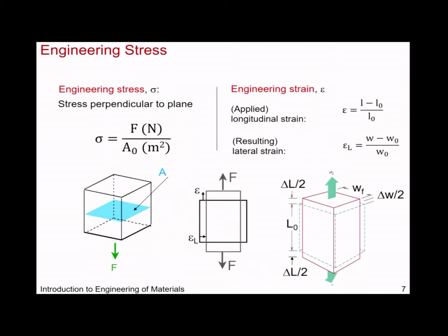So you'll see these equations quite a bit again and again. If you're applying a load in tension here with some starting material that has cross-sectional area A0, you can imagine that as it's elongating, there's going to be some contraction laterally, to conserve mass, right? You're elongating it, so now laterally it's contracting. And vice versa for compression, if you're squeezing something, you can imagine increase in the lateral direction as well to compensate.